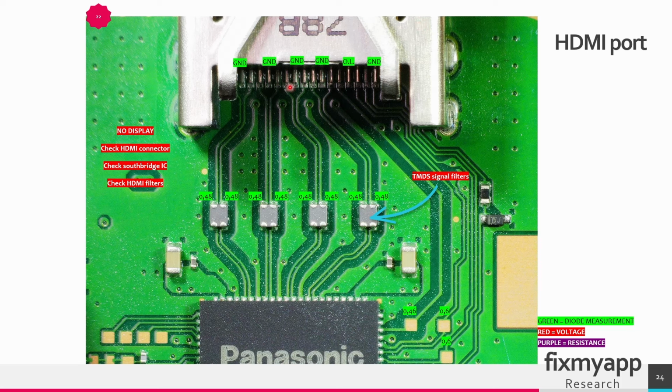You have to check if all pins are connected. You have to check the Southbridge chip. And also you have to check these filters. These filters should have a continuity between those two pads, but not sideways.